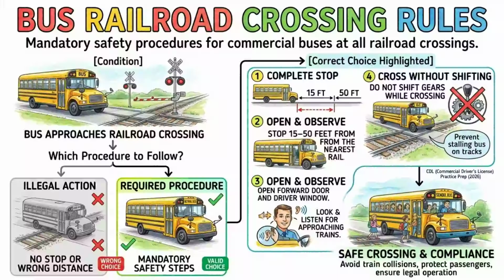Front-end header boards, sometimes called headboards, are a critical safety feature when transporting heavy cargo on flatbed trailers. A headboard acts as a strong physical barrier placed between the cargo and the back of your cab. If you have to slam on your brakes suddenly in an emergency, the headboard prevents heavy items like steel pipes or lumber from shooting forward and crushing the driver compartment. The exam will want you to recognize that the primary purpose of a header board is to protect you, the driver, from forward shifting loads.